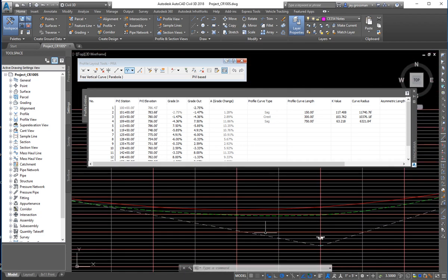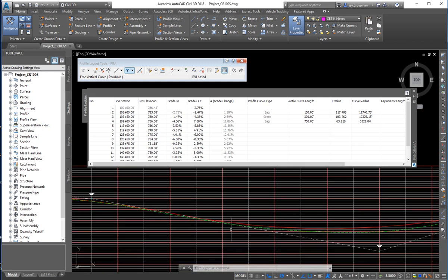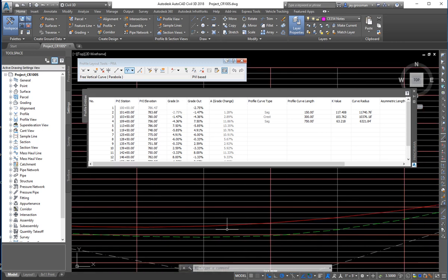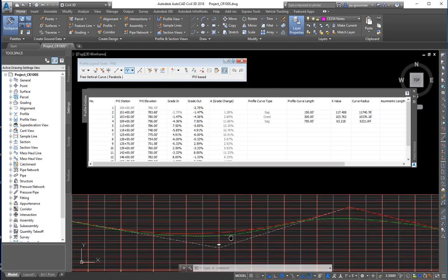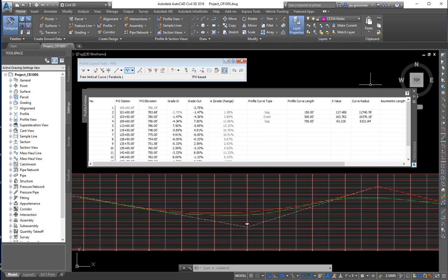Problem is, we finally got above 60, the K value. We're pretty high through here. We're 2 feet above the existing road right through there. Tie in there. We should really lower our elevation a little bit to match better, but when we do that, we're going to lose some K value. Let's not take too drastic a step.